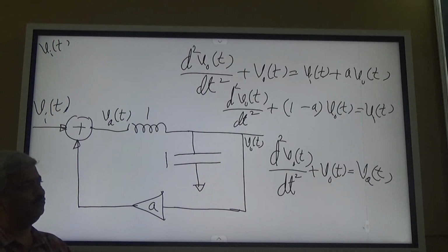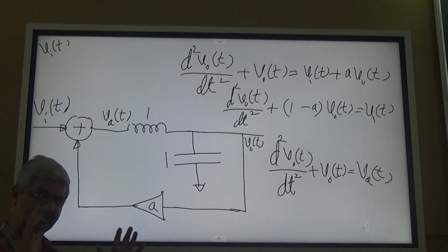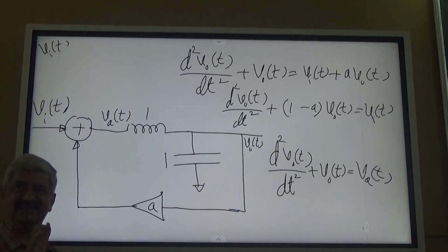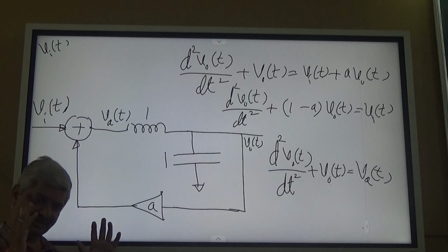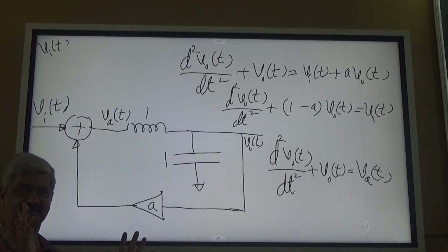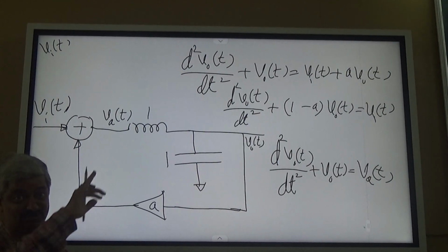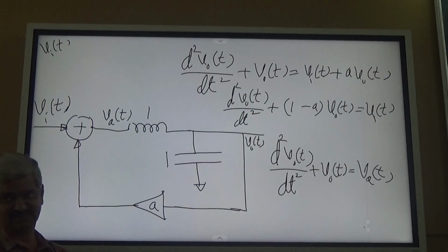So we must be able to get full-fledged hands-on practice constructing differential equations for any circuit which consists of R, L, C, then scalar or amplifier and adder. Only scaling is of more use unless you are able to use an adder, because feedback is needed. Otherwise, it doesn't serve any purpose.